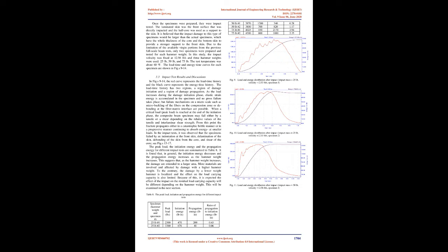5 is linear, the second part is nonlinear, and the third part is again linear. During the test, small wooden pieces were used to increase the space between the specimens and the bottom fixture. During the test the wooden pieces deformed and the load deflection graph fluctuated, Fig. 5. The second test was conducted using metal pieces, the roller, and the graph looks very fine in the linear portion, Fig. 6. For 3-point bending test, core shear strength of the beam specimens was calculated using 1.